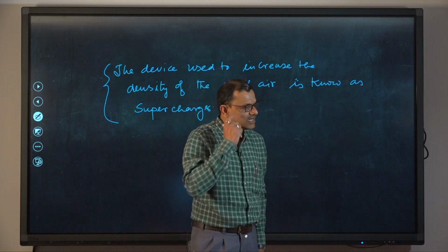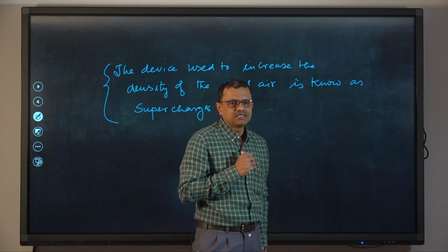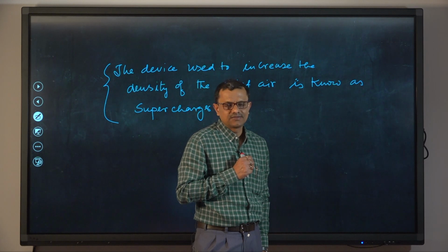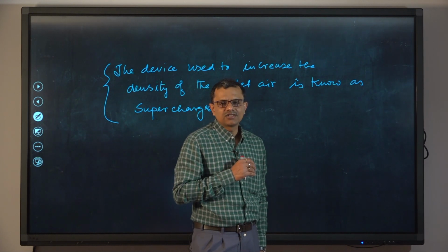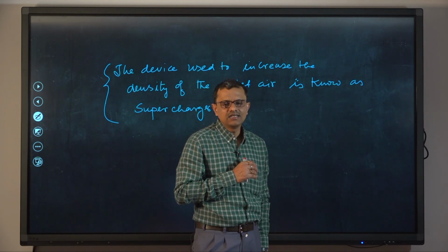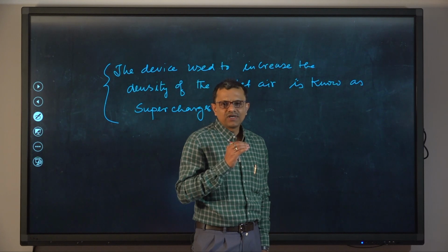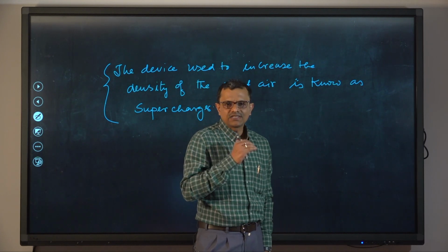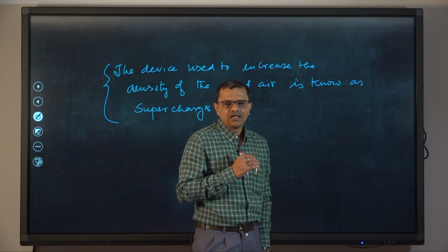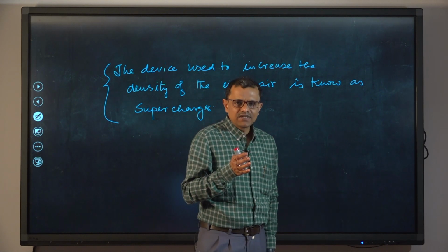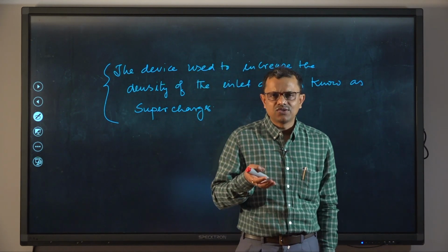Now the question is, if we use a supercharger for the SI engines, whether it is a 2-stroke cycle or 4-stroke cycle engine, then supercharging will increase the pressure of the intake air. Now, that air pressure will again increase during the compression stroke.